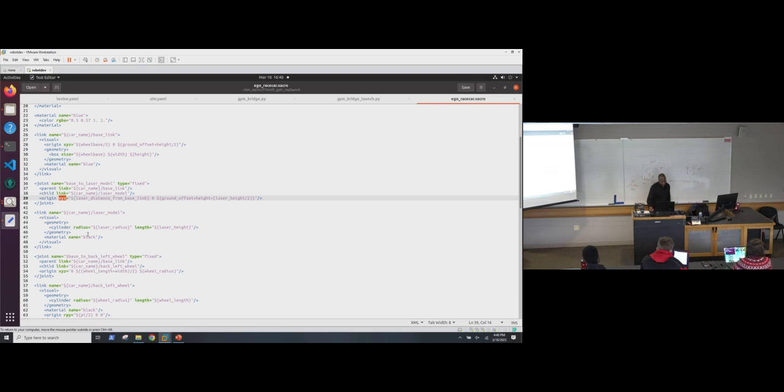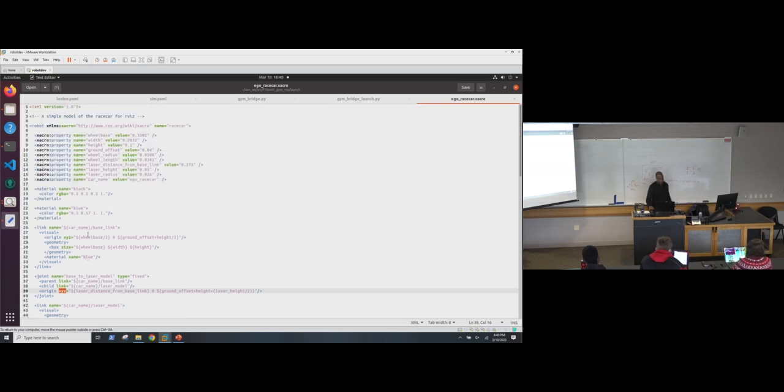Where do you set the origin on the car? The origin is always going to be the base, and you can't set the origin, so you set everything relative to the origin. So that origin is always going to be the 0, 0 position there, and that's usually the centroid of the vehicle. The center. Yep. And then you can measure, okay, where the LiDAR is relative to it. And what I do is bring it back up and make sure that it makes sense in RViz.